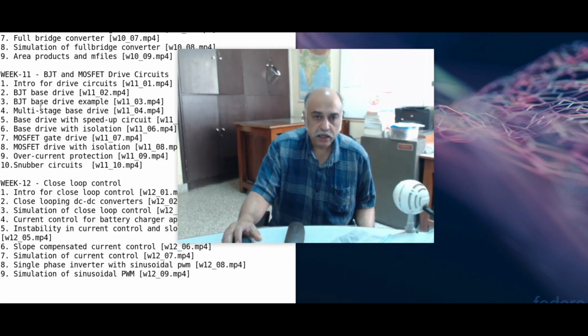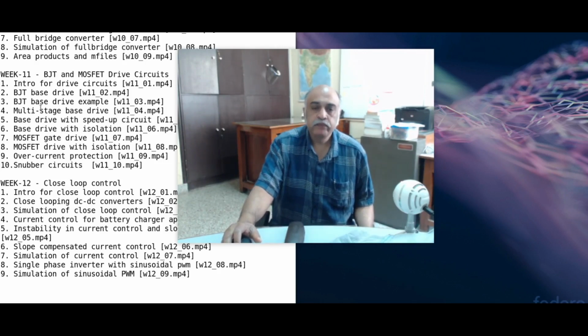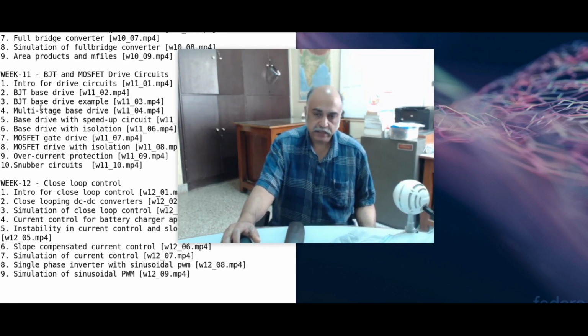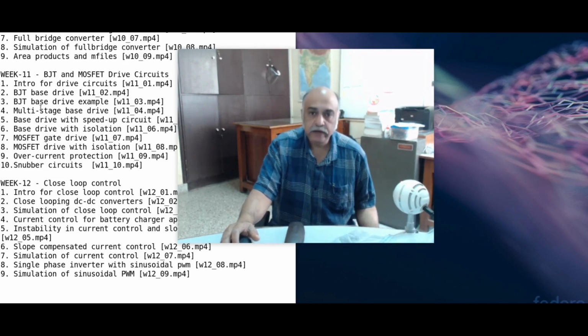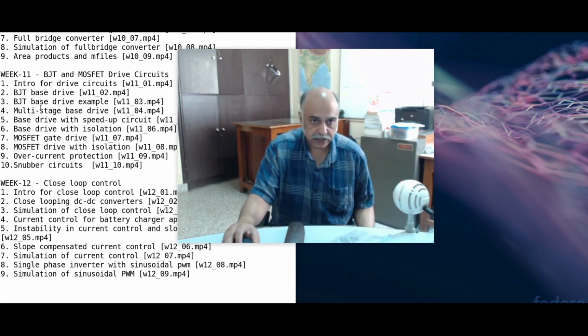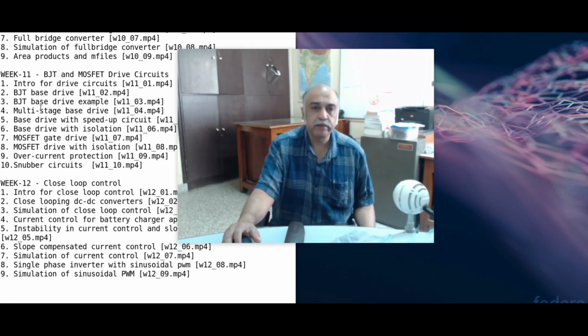As that is not much supported, we will migrate to KiCad as the schematic capture front end. So we will capture the schematic using KiCad. Then with the captured schematic we will generate the netlist from KiCad, and that netlist will be passed on to ngSpice for further simulation. So that is the change in approach that we will be using.